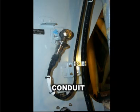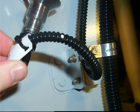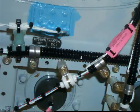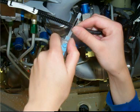Concerning the conduits, check there is no liquid inside the conduit by moving the conduit lightly. Make sure there is a drain hole, when necessary, at the lowest point of the conduit. Ensure the drain hole is not obstructed. If necessary, make a new drain hole with the appropriate tool.